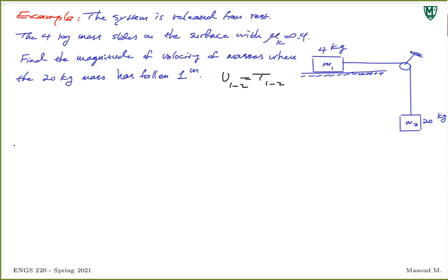If you're asked to find the velocity vector, maybe you can probably guess it based on the direction of the motion. But typically, that's where you actually have to go back to Newton's method. Or we'll see later on, if it's an impact, you can still use energy method, but that's a different story. All right, let's stick to this. Magnitude of velocity, asking for velocity. So that's a sign that probably energy method can be helpful for us and make our life all easier.